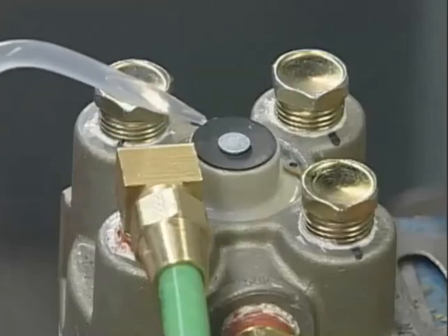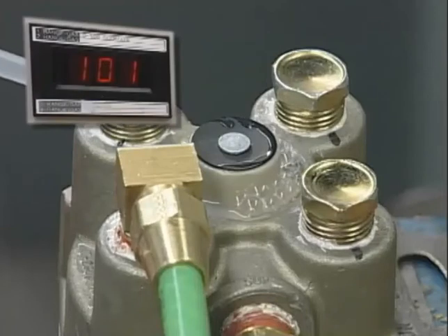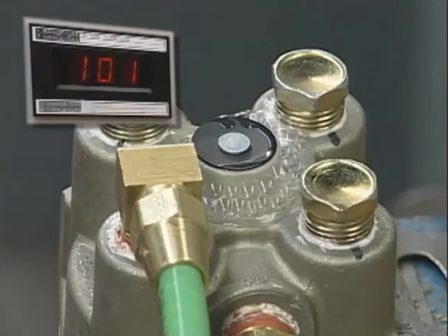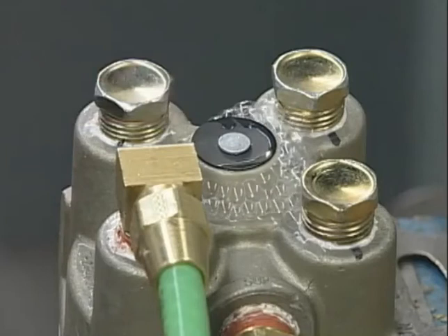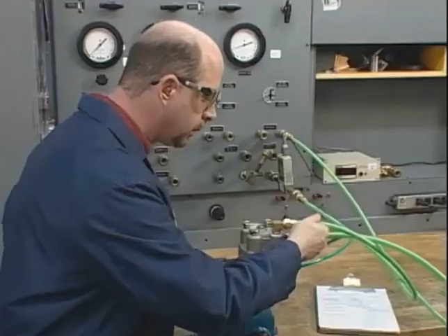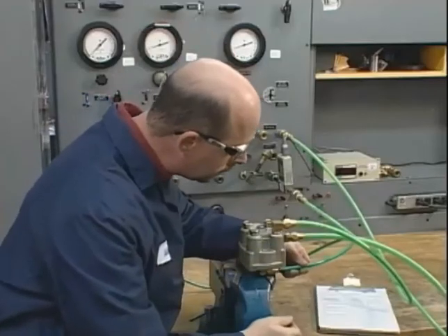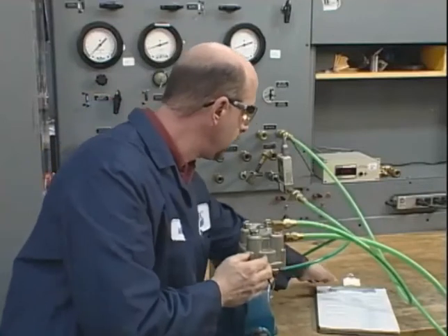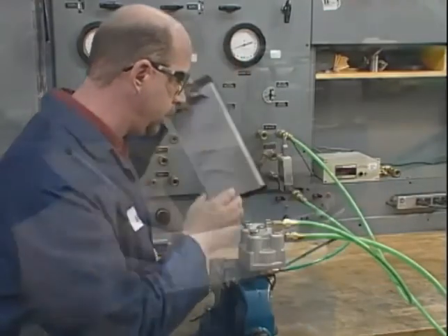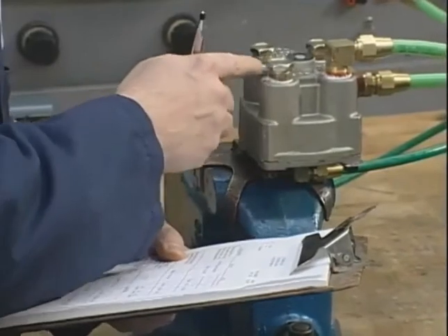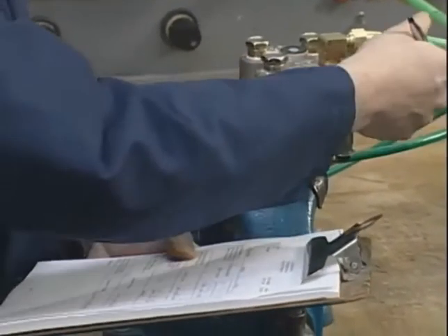Now, here's what air leakage looks like around 100 SCCMs, which, by the way, is well within the specs for valves in service. Whether an air leak of this size would call for further action might depend on the cause and/or the location, but it's definitely too small to cause leak-down test failure on its own. You'd still have to look for the primary leakage source.